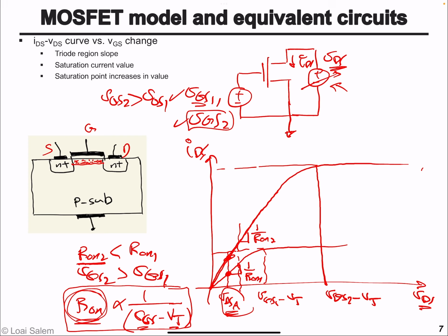And since the excess voltage that's higher than the threshold voltage is basically accumulating more electrons than what's needed to just cause enough conduction between the drain and source, the value of VGS minus VT, we call it V overdrive, VOV, because it's in excess of the threshold voltage. V overdrive, we also call it the effective gate to source voltage. So V overdrive or VOV.